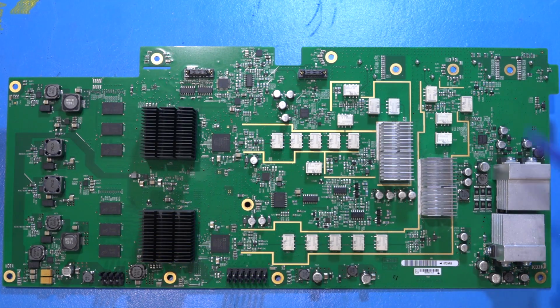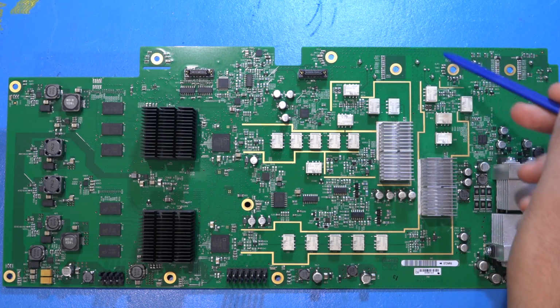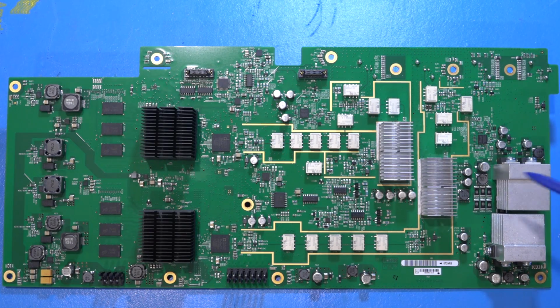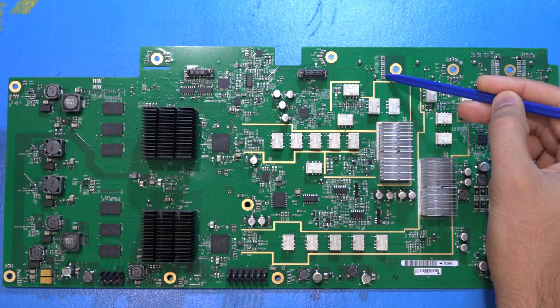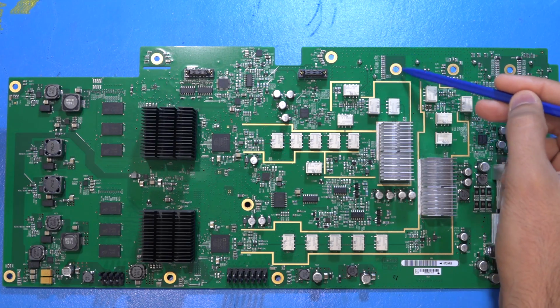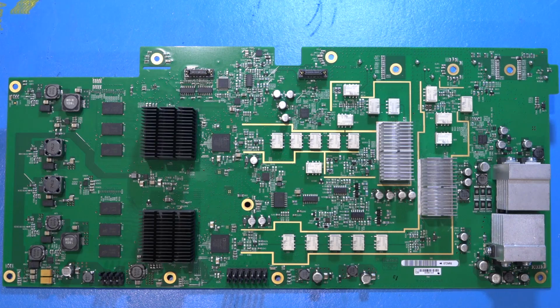And some power connectors. Oh, and this is interesting. This is where the screws go that connect this to the chassis. And this is a grounded pad essentially because it's connected to the screw. But you don't necessarily want to treat it as a normal ground. Look at all these capacitors that are here. This is an entire capacitive network that couples this screw to the rest of the ground. And this is very carefully designed to get a precise frequency response of the ground.